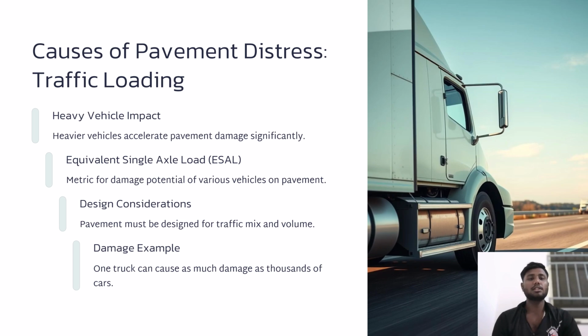The next one is design consideration. Pavement must be designed for the traffic mix and volume, because of higher volume and heavier traffic. Damage example: one truck can cause as much damage as thousands of cars. Because of that, we have to design our pavement with respect to trucks.